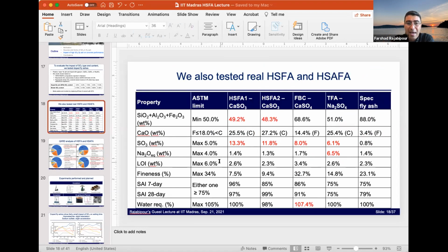So these are parallel issues. Of course, if you have a high LOI fly ash, especially if you have variability in the LOI as a function of production time, you can cause problems with air entrainment and non-reliability of your strength and your air, and all of this stuff that we already know.